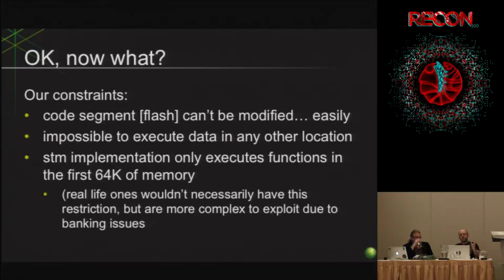By default, the MOVEX opcode basically says, hey, grab this over here, and I want you to move it into Xdata over here. When you flip a particular bit, suddenly the MOVEX command operates differently. It grabs from over here, and then it will actually write to Flash, assuming it meets the constraints we talked about earlier: you can only drain bits out of a field. You can't add bits in. So you've got all these steps to go through, and it makes it relatively difficult, at least if you're doing it from a gadget perspective, right?